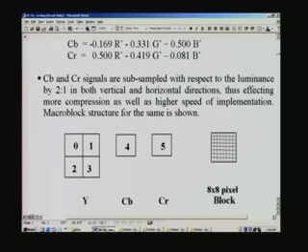And this is what is termed as a block, and 4 such blocks would constitute a macro block, that is what is here, and each of them represents a block here. So suppose you want to transmit, process a full color. What you need to do is, instead of 4 blocks here and just 1 block shown here for the color component, we actually need another 4 here and another 4 here. That would take a total of 12. You have to process 12 blocks.